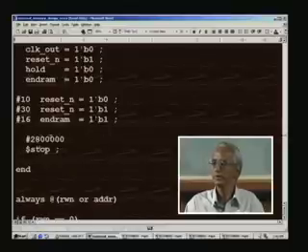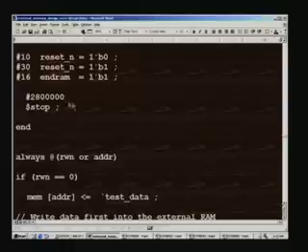If you multiply, you will get this figure with 1 cipher less. The extra cipher arises because each clock cycle is 20 nanoseconds. So you multiply that result by 20, that is 2 into 2 into 20 into 64K must come close to this. That is the reason why we have such a big value here, and after this value the test bench will automatically stop the testing.